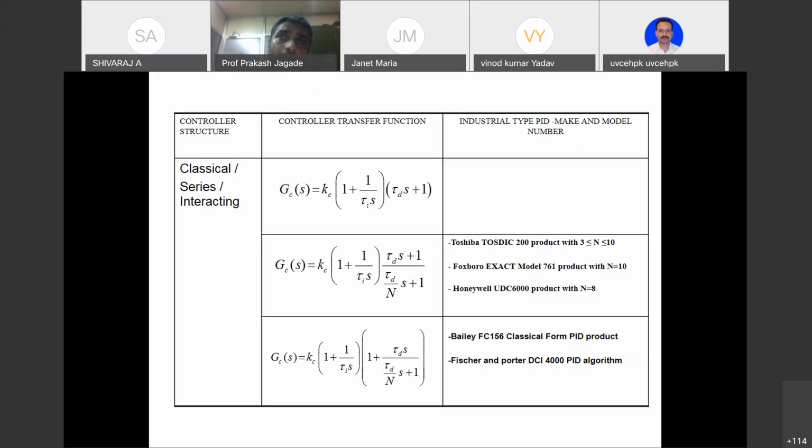That depends on how many parameters are in your PID controller transfer function. If there are 3 parameters, then you need minimum 3 specifications, for example, your closed loop gain, your closed loop time constant, settling time. The user has to specify them properly, and as a result they get a unique solution.